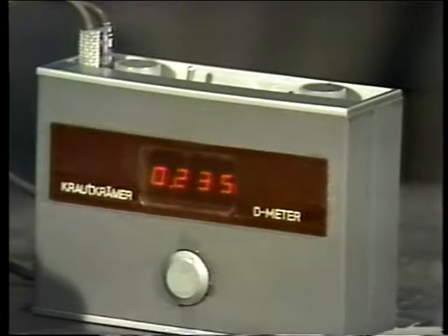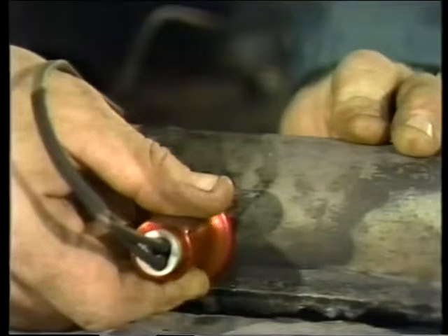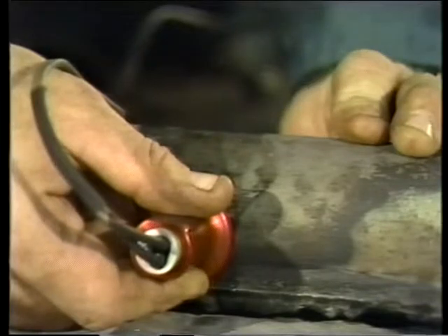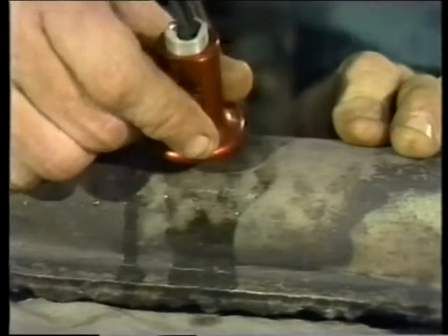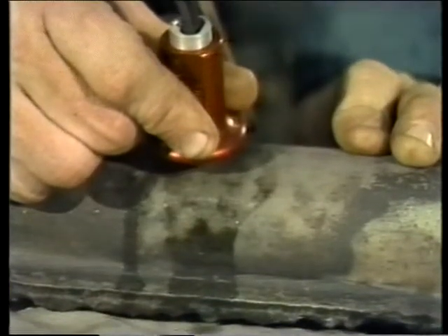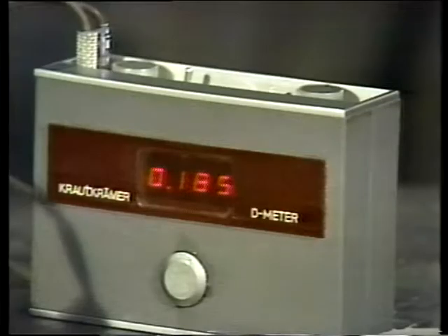Sometimes you may have to take measurements more than once because readings can vary if you don't use firm, uniform pressure to hold the probe against the material. Doing it right so you'll get accurate, consistent readings takes some practice. When you move the probe over an eroded spot, the readout changes to show the change in the thickness of the wall. Ultrasonic testing is a valuable technique for locating hidden defects.